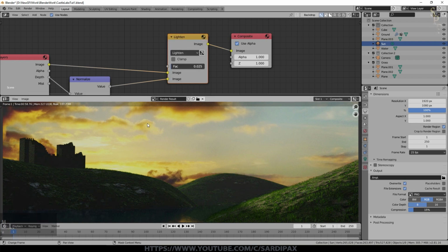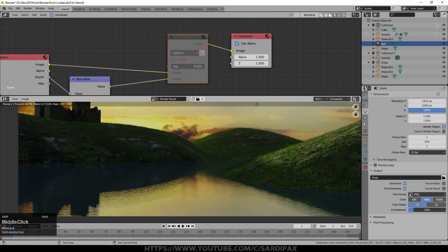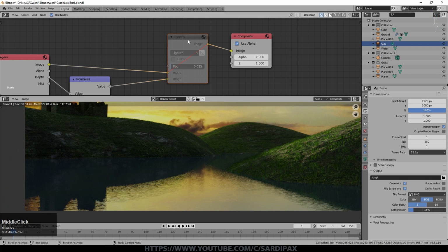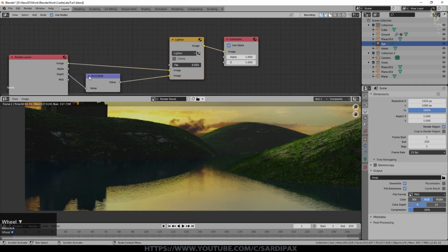And what you can basically see is the very dark areas have become a little lighter if they are further away. There's very little effect here, perhaps a slight one. And now let's have a look at the water, which is where you can get some problems. Overall, I think that's working quite well, but let's try the mist pass now. So we'll just put that into here. And obviously mist is at a different level, so we may need to increase this just to get that to show up. So I've got that at 0.15 now.